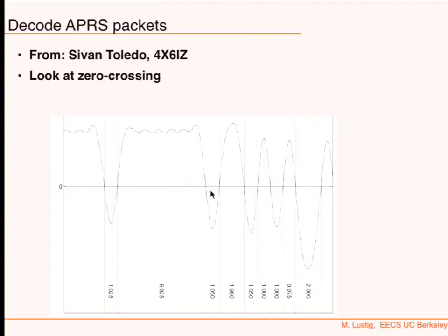And so you can just create a state machine, count, figure out how many bits, and just aggregate them. So it's really easy to figure out when a packet starts and stops. And that's how we implemented this for you, by the way. We implemented this scheme. You only need to give it the NRZI, and then it goes through and very simply implements this type of decoding. Okay? Yeah, you can see the code, of course.